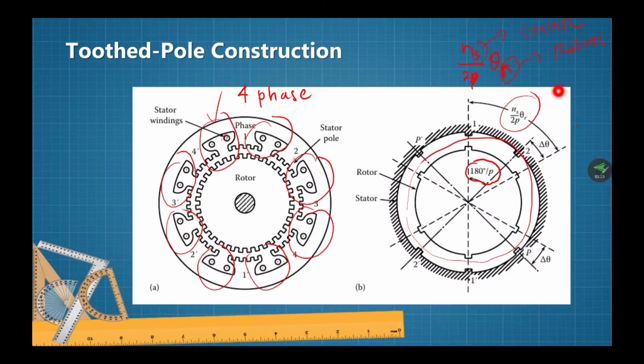and this is the stator pole. The stator teeth are equally spaced, but the pitch or the angular spacing is not identical to the pitch of the rotor teeth. In the tooth stator construction, Ns in here represents the number of teeth rather than the number of poles in the stator. The number of rotor teeth has to be increased in proportion.